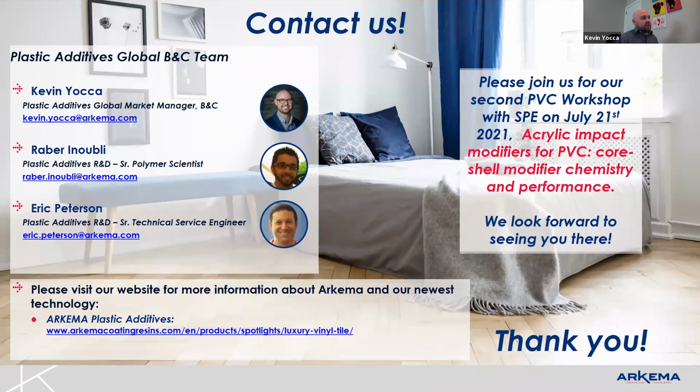Yeah, I think, when we talk about injection molding in our lab in King of Prussia, we often want to injection mold parts for customers to do testing for them, and we have to pelletize it first. I have done some powder injection molding, but it's really not a great idea. Typically what we'll do is make some kind of pellet first. And so built into what you're doing when you make a pellet is you have to assume that you've already started the gelation process. So what might that look like?